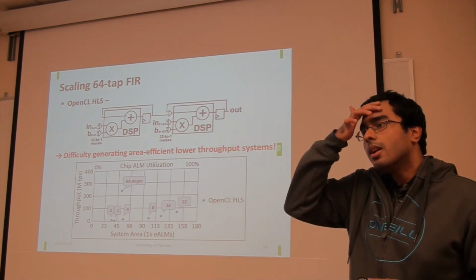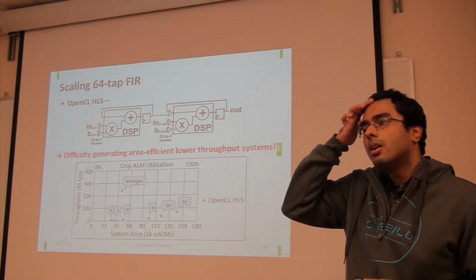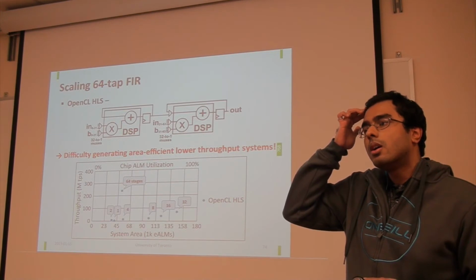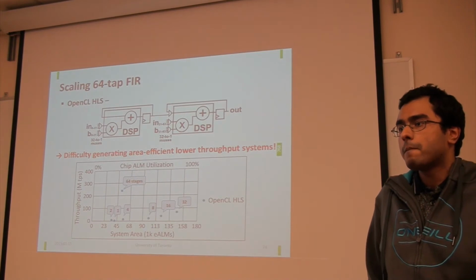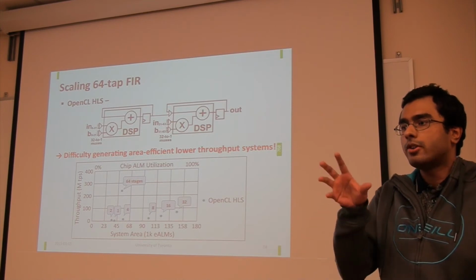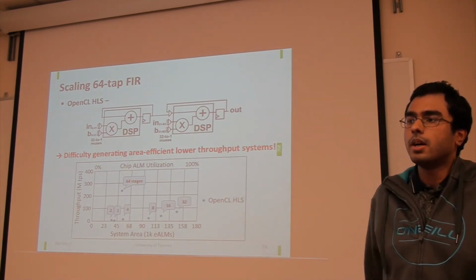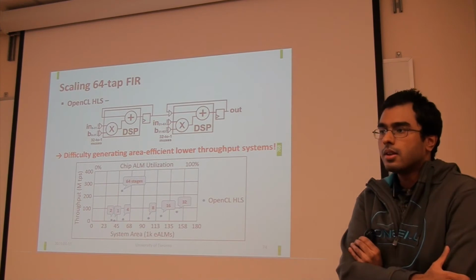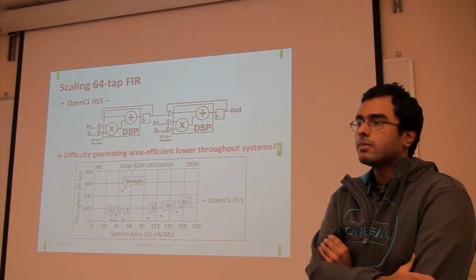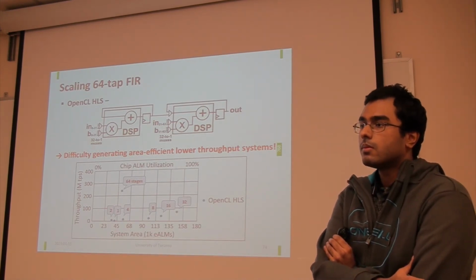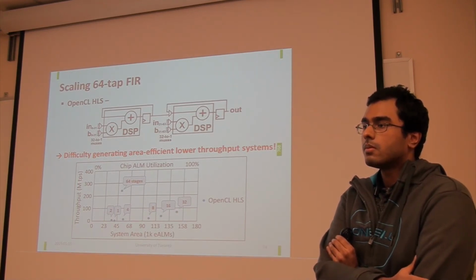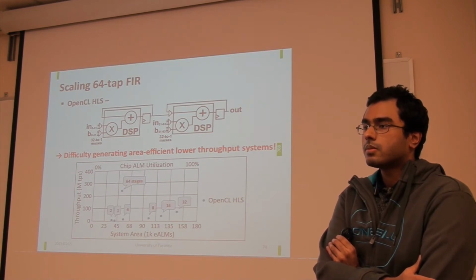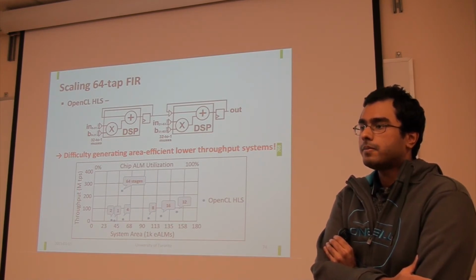Go ahead. Quick question. One of the things with OpenCL is you necessarily need to copy the data to memory so you can operate on it. To me, that's an extra copy and not necessarily that efficient for, say, streaming behaviors. So are you just talking about copying from host to device? Yes, that has to be a necessary step in OpenCL in order to use the data. So I'm just wondering what kind of changes you would have to make to the tilt architecture to process streaming data, say coming from either PCIe or Ethernet or any other streaming source, without having to go to memory first.